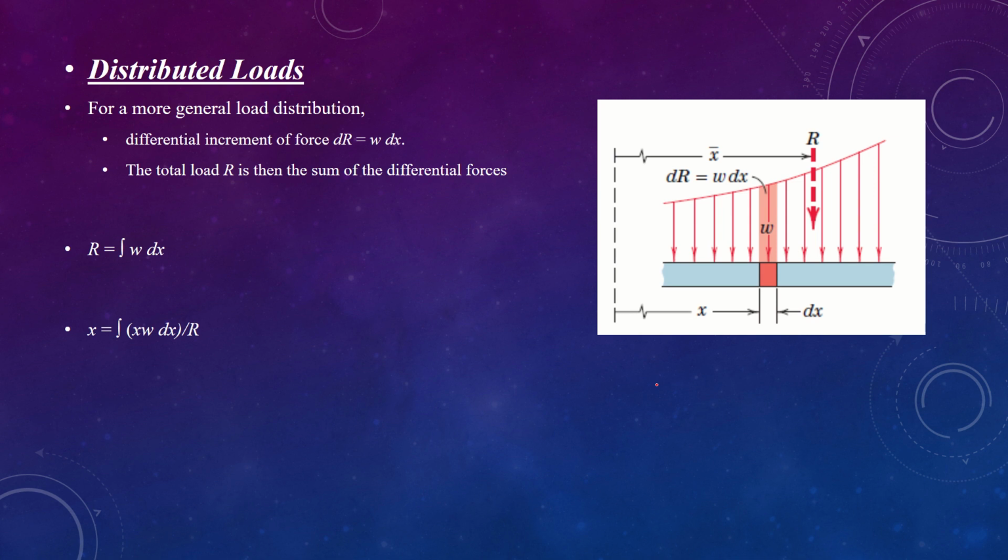Now that is how you define your weight, a uniform weight. But in this case, simple, a small slice or small weight W, that is load per unit length, acting on this beam right here. The cross-sectional area, the length it is acting on, is dx. So this is going to generate a very, very small reaction. So you can say my dR is in fact W dx.